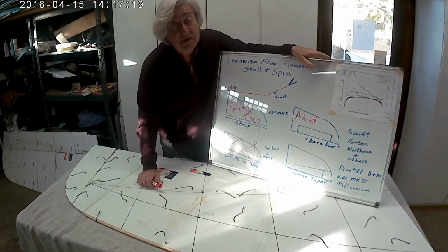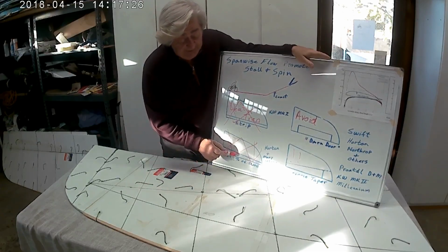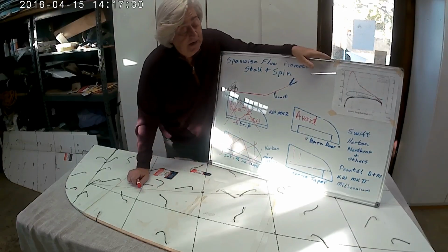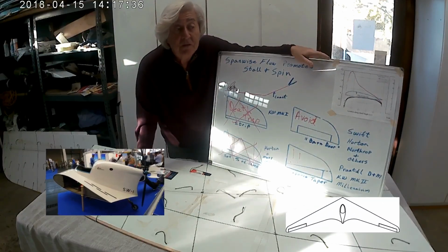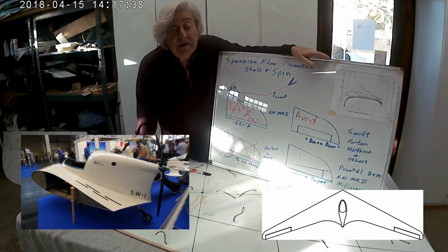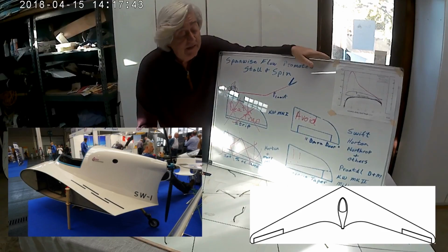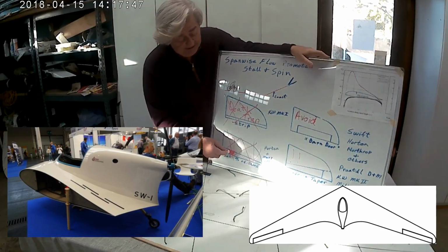If they're still working on it, I'll tell you again, you need to get rid of this elevon shape. It is a death trap. There's another one that's in the works. The guy's built the fuselage, mounted the motor, he's got the wing carry through. He's basically got everything but the wings. And from the drawings that I've seen, he seems to have something between here and here.